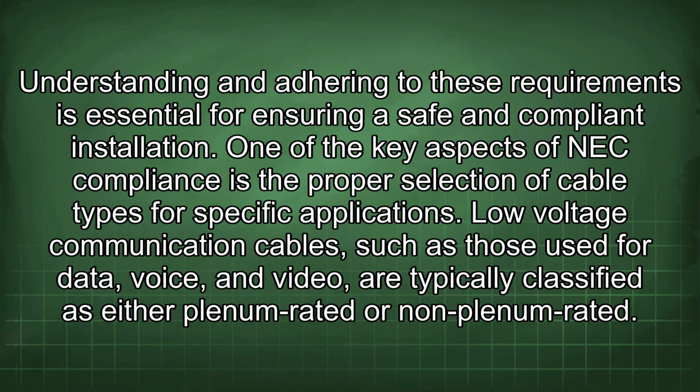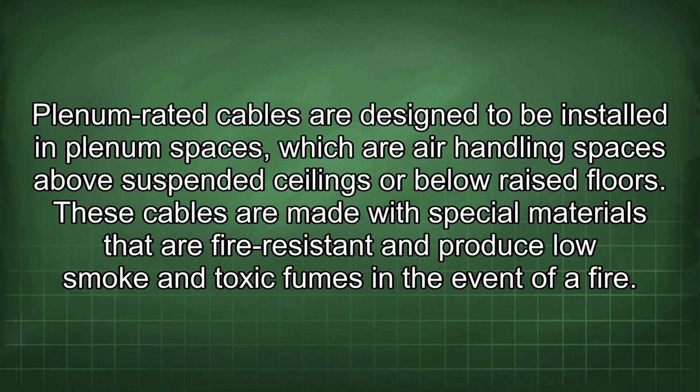One of the key aspects of NEC compliance is the proper selection of cable types for specific applications. Low voltage communication cables, such as those used for data, voice, and video, are typically classified as either plenum rated or non-plenum rated. Plenum rated cables are designed to be installed in plenum spaces, which are air handling spaces above suspended ceilings or below raised floors.